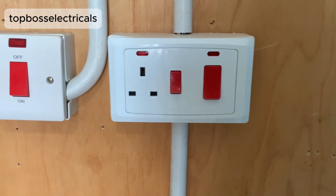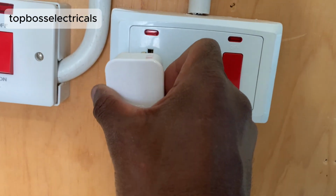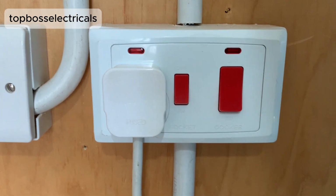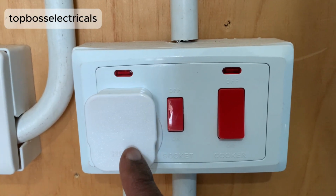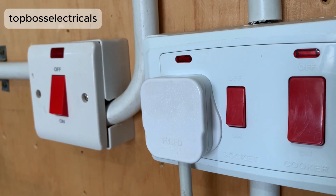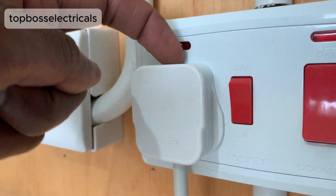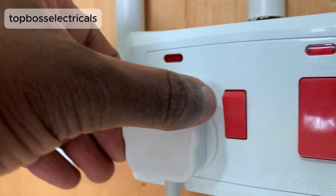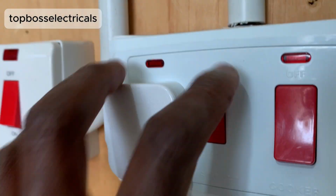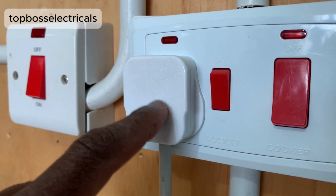In many cases, you find that if this top plug is connected or fed directly here, and then it is from an electric cooker which draws a lot of current, it will start overheating because of the loose connection. That definitely leads to a very, very bad experience, whereby at the point where the customer has to change everything, which is plastic, you find that this is plastic, this one is also plastic, they are glued together and the only option is to knock them off or destroy them.